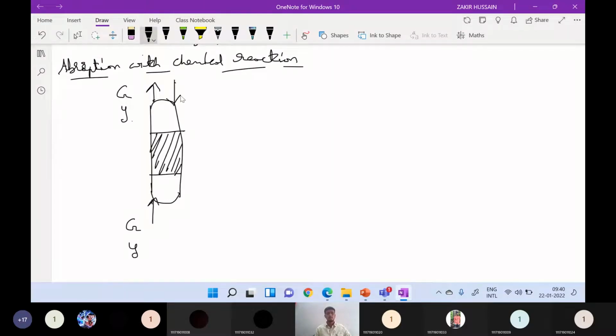Why? Because we are not deriving anything here. So this is liquid which is entering countercurrent to this one. The solute composition of the liquid is X, and here also some solute composition X. Usually, since this is a gas, to measure the gas composition it is very convenient to measure the pressures or partial pressures. So P can be used. Usually the P star or PE, the equilibrium partial pressure, will usually be zero. Why? Because a large part of the solute will be solubilized into the liquid, because there is a chemical bonding between them due to the chemical reaction.